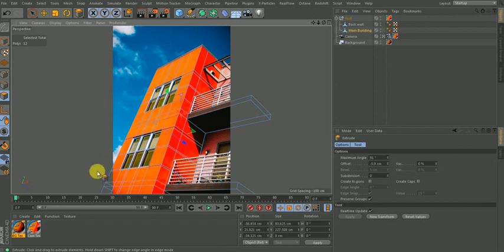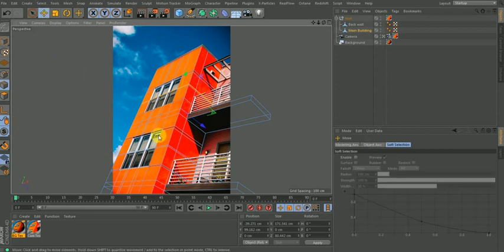But if you notice for this, if I go to edge mode, you can notice this is where this top part ends. So what I did was to select this edge, so I can start from here. Okay, maybe here. Alt D to put them out. This and this.